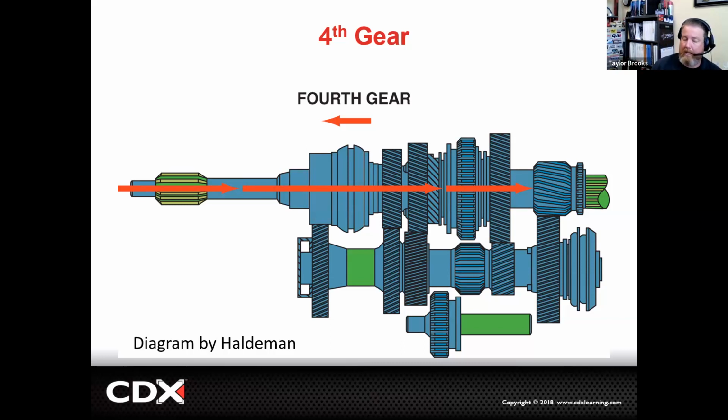So the best way to look at this is fourth gear, or whatever gear direct drive happens to be, is just bypassing the transmission. It's going right through it. And there's no torque multiplication, nor is there any speed multiplication. So first through third are underdriven ratios where there will be a torque multiplication. We will have higher output torque than there is input torque, and that results in a smaller input gear driving a larger output gear. For direct drive, it's 1 to 1. So we have the same diameter versus the same diameter. In the sense of this, we don't have any diameter because we're just locking the shafts together.